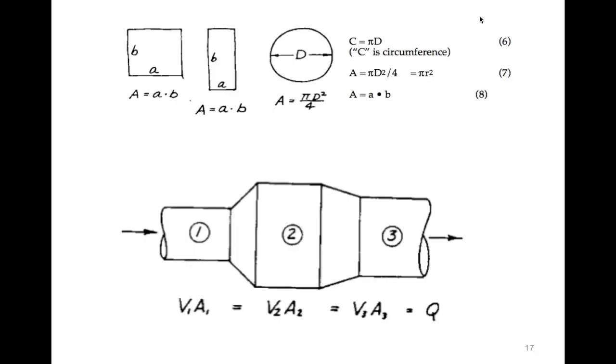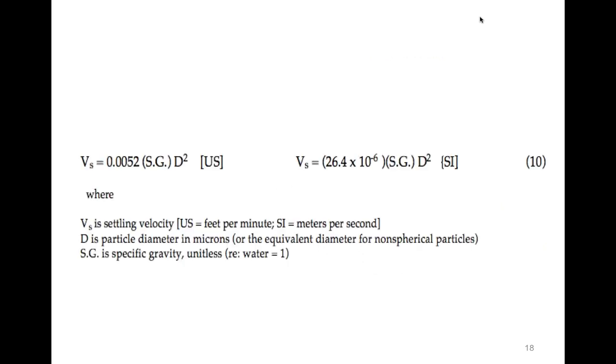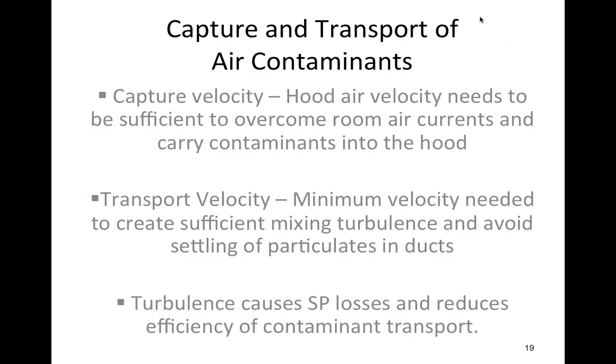Okay, there you go. Now here's another duct. Not all ductwork in a system is going to be the same size. This is circular duct, as it happens. Circular duct is a little more complicated because we have a formula we have to use to calculate the area. It's not as simple as A times B as it is with a rectangle or a square.